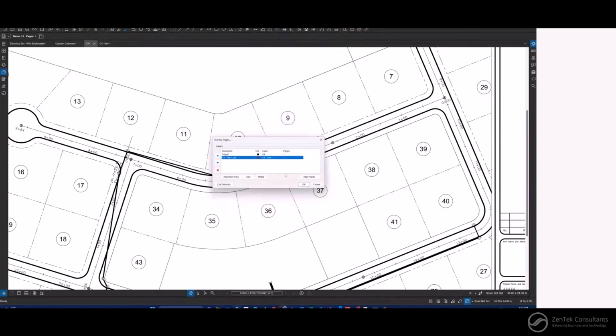And here's where we can also align points. So if you have 2 different size drawings, this is where you're going to want to align the points. And aligning points, they'll say, please choose 3 different points. Some recommendations for this is use column lines. You can use the corner of the drawing. Column lines are usually my go-to, though.